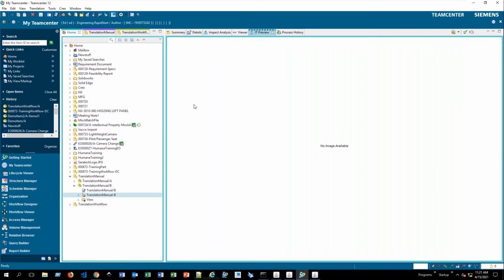And Teamcenter is going to take care of the rest. Now, before I show you the result, let's go ahead and pick off another translation just so that we can also see our JT file. So I'm going to go ahead and use that NX to PV direct, and again, select finish.